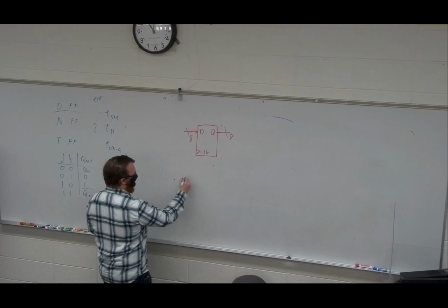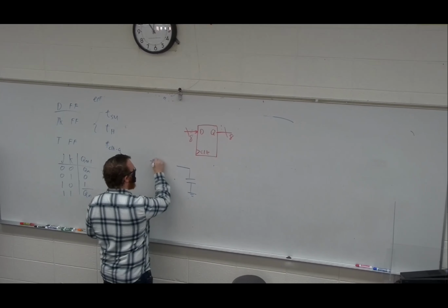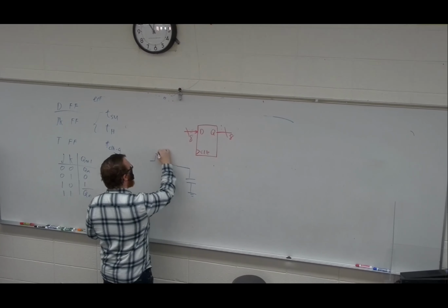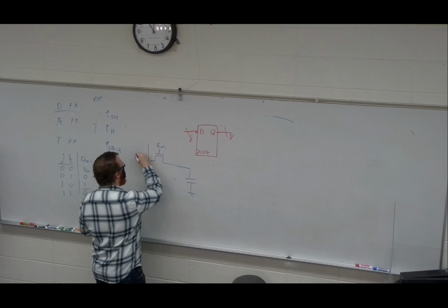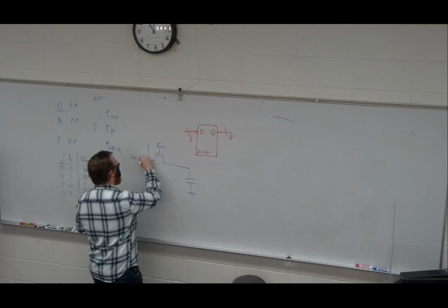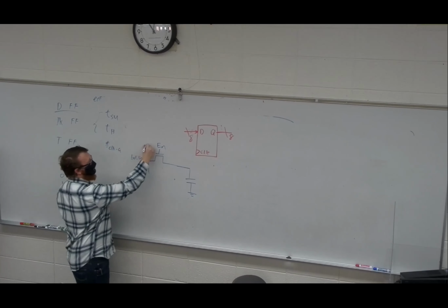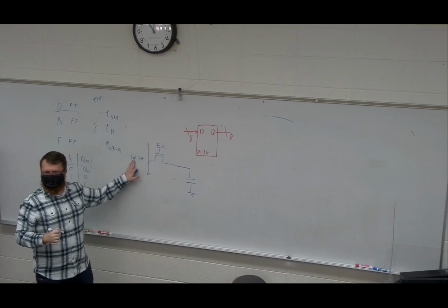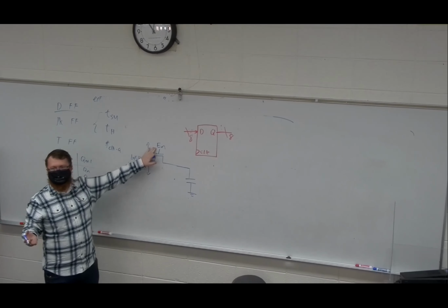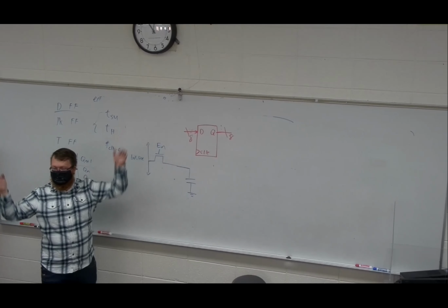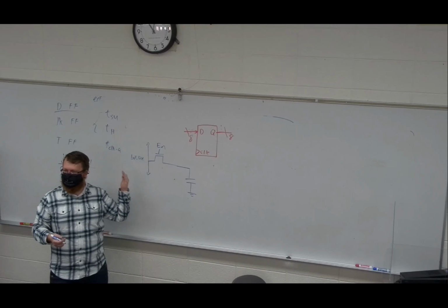So if I take a capacitor, here on this side, this is called our bit line. It's carrying data for us. This is a transistor that functions as a switch. When I raise this switch to enable, it turns on, allowing whatever is on the bit line to either be stored in or read out of this capacitor.